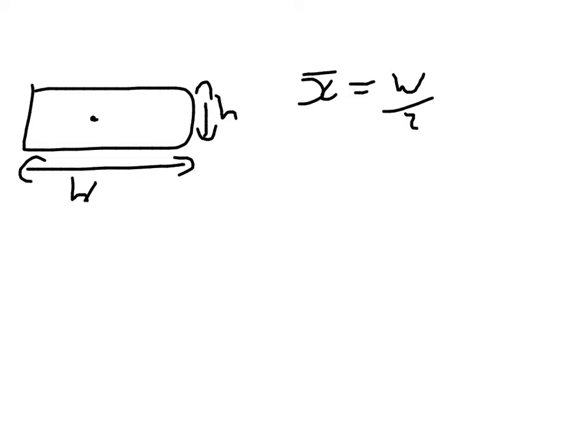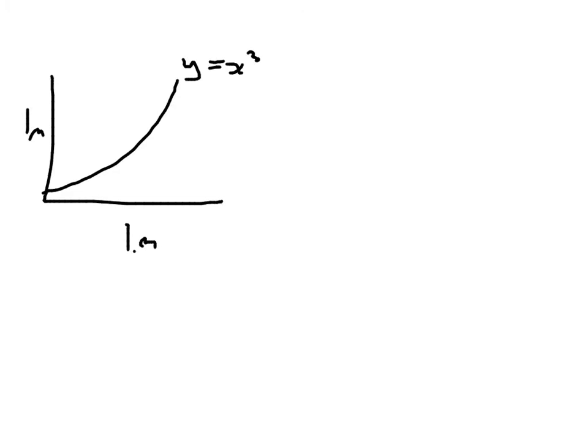But if we go on to look at the example that begins on slide 11, I'll just briefly sketch it and then I'll talk you through it. So we're asked to find the area of the bit that I'm just shading in now. Okay, so we're asked to find the area of that shape. What we're going to need to do, if I just remove some of those lines, this bit I've just shaded in is still a bit we're interested in, I just need to sketch onto it. We're going to find a series of different pieces of information. So we know that, for instance, the x bar coordinate is the integral of x tilde dA over the integral dA.